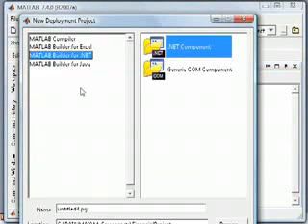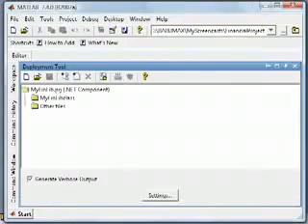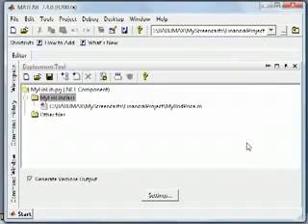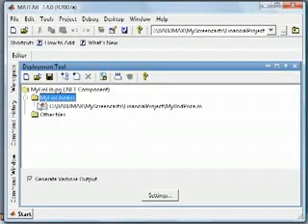Now the first part is we need to create a project. So I'll just say myfinlib. I'm selecting here MATLAB Builder for .NET. Now I need to add files, myBNDprice. So I add that. I'll just save this project.